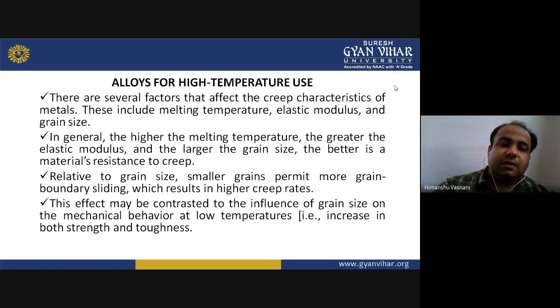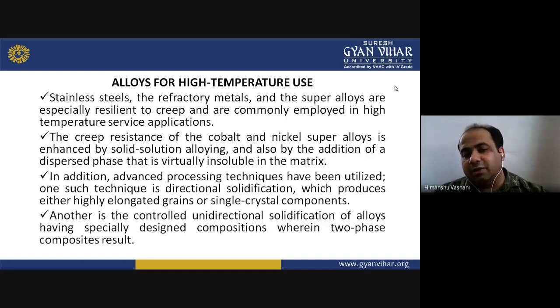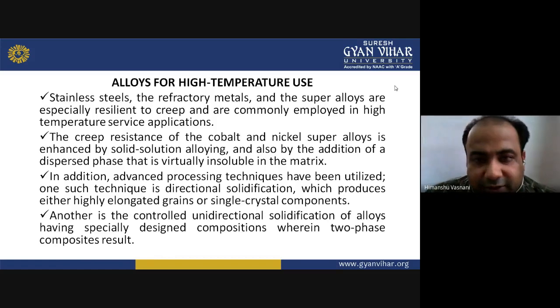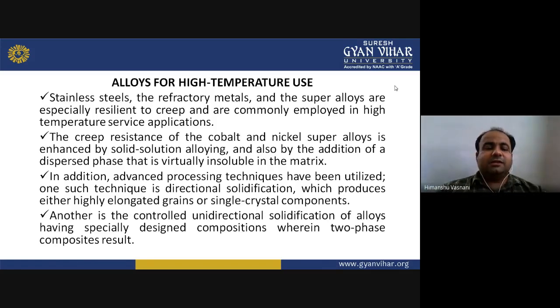Stainless steels, refractory materials, and superalloys are especially resilient to creep and are commonly employed in high temperature service conditions. You can understand that various industries use these resilient materials. The creep resistance of the cobalt and nickel superalloys is enhanced by solid solution alloying.